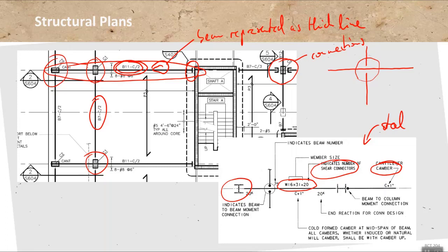Now, that's the primary structural system, so those are the beams that hold up the structure, but then between those is a floor system. In our case, it's cross-laminated timber. This could be a steel deck, could be all kinds of different things. And then you need to show the span direction for that floor system.